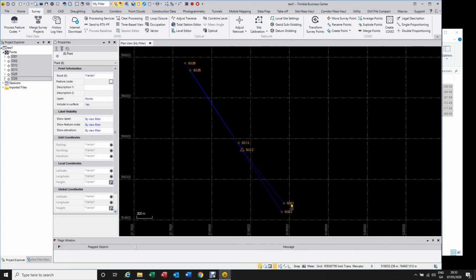We were observing them for almost an hour, and then for next step these baselines will be control points, and everything we traversed with the total station will be calculated from them, but these will be then all control quality.